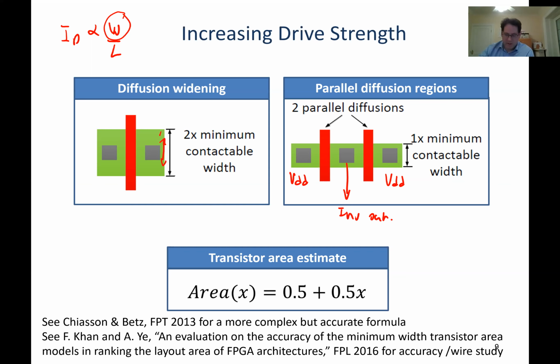And what I've got now basically is 2 transistors in parallel. Each of them has the minimum width. Together, they have twice as much drive strength. This also added area, but it didn't double my area because if I had made just one transistor, it would have ended around here. Instead, I've added this extra stuff onto it. And I don't have to increase my spacing to the next transistor either. So they both increase the area, but not double.